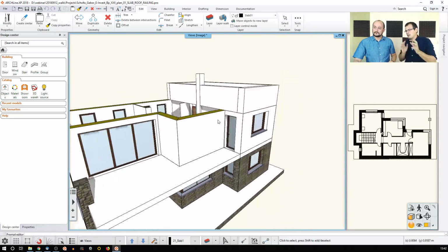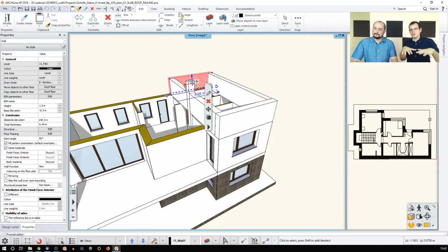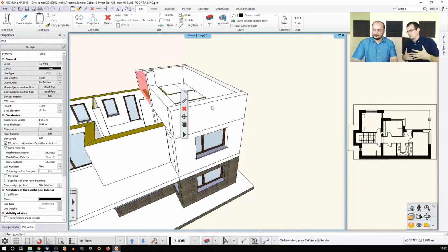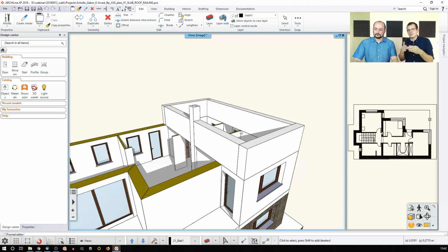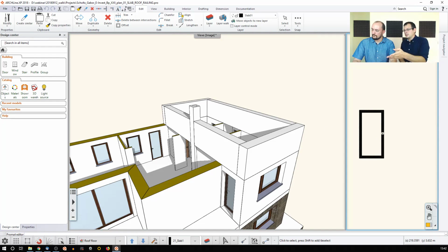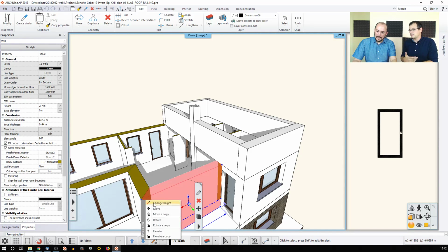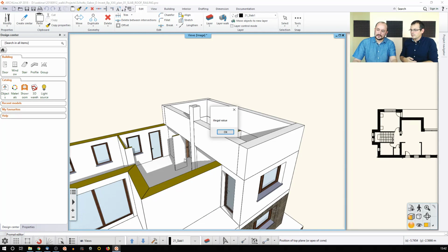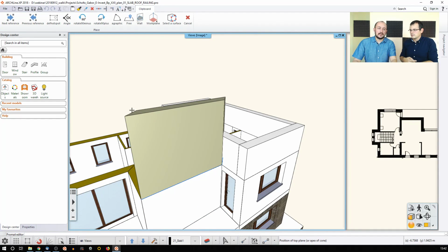During our webinar on roofs, we showed how you can put a roof on top of a wall, and the roof is going to cut the walls. Like you just said, but there are some scenarios when you want to extend walls upwards, but because they are T-connected, they're not going to be good enough. Now, in this situation, maybe you can demonstrate it here. If you extend this wall up here, although it's not that realistic, let's just change its height. Oh well, I used the wrong value, but let's say I would like to change the length of